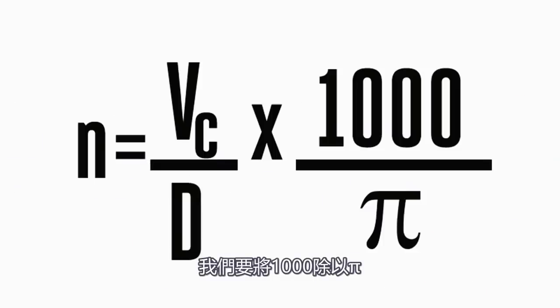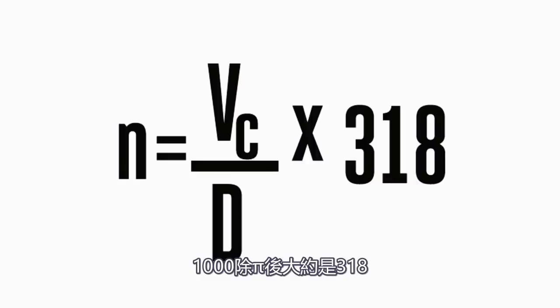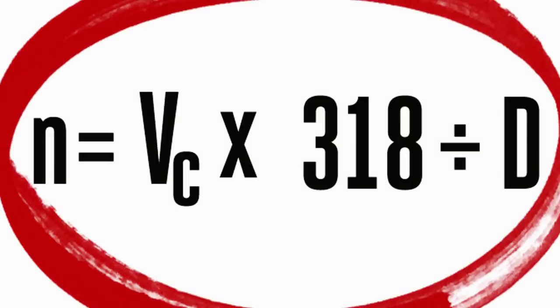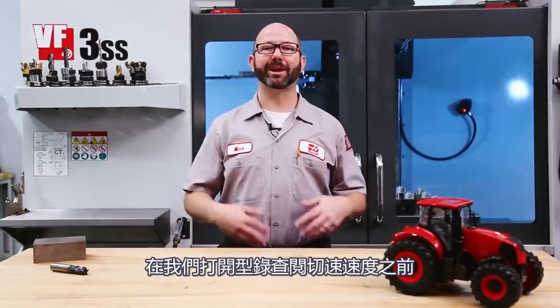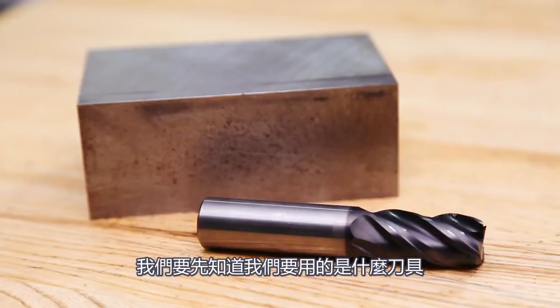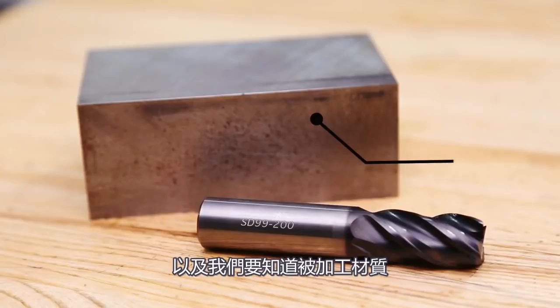We're going to divide the 1000 by pi. 1000 divided by pi is about 318. We're going to go ahead and use this simplified formula for the rest of the video. Before we open up our catalog and get our cutting speed, before the tractor even leaves the barn, we need to know exactly what cutting tool we're going to use. And we need to know exactly what material we are going to be cutting.